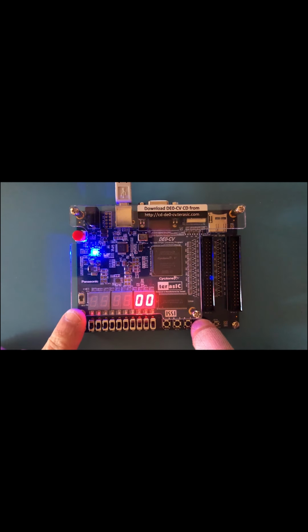Now if you press this, probably nothing's going to happen because we're cycling through the different stages of the microprocessor. The first cycle is the instruction fetch, the second one is the instruction decode, the third one the data fetch, the fourth one execute, and the last one is the result write back, where the result of the ALU is written back to the RAM, in this case our reg file, or makes a jump, either conditional or non-conditional, to the program counter.